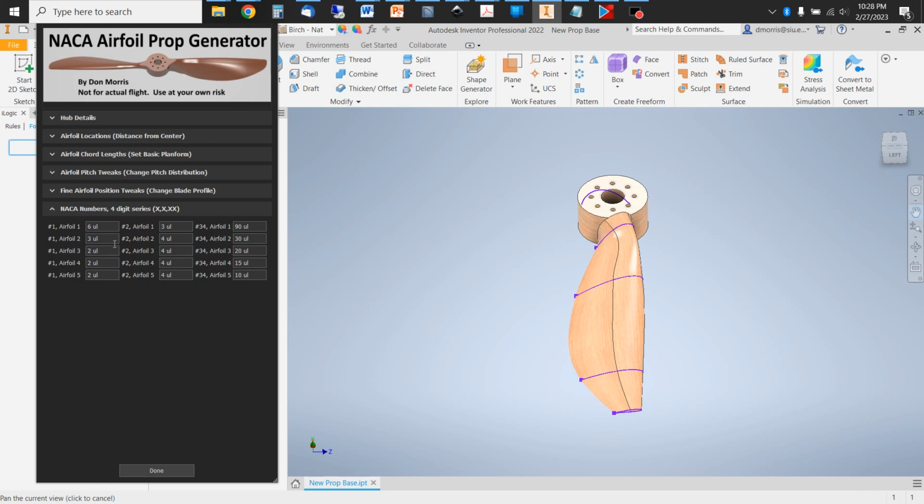And then we're going to move into our airfoil number 2, which is not possible with the NACA schema, but there isn't any reason why I can't go ahead and go with halves on my mathematical calculation. So we're going to go with a 4.5, 3, and 50%.